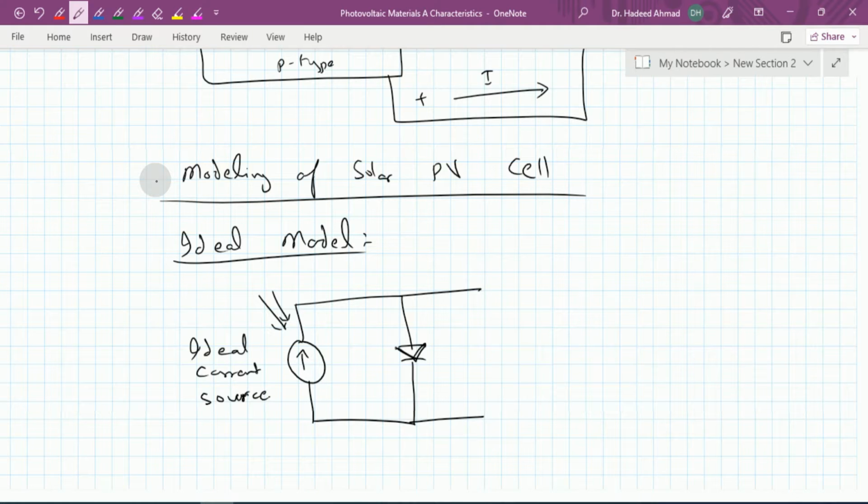And of course, from the theory that we have studied so far, only those photons contribute to the production of electricity which have their eV, or electron volt, or band gap energy, more than 1.12 for silicon. So there are 2 points of interest for any given solar cell. The first thing is, what if we short circuit these two terminals?